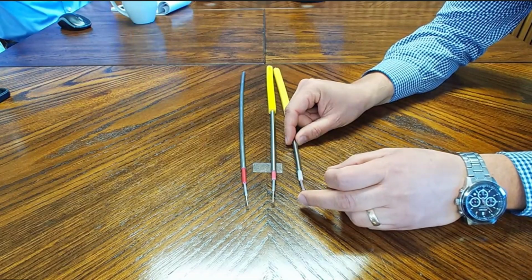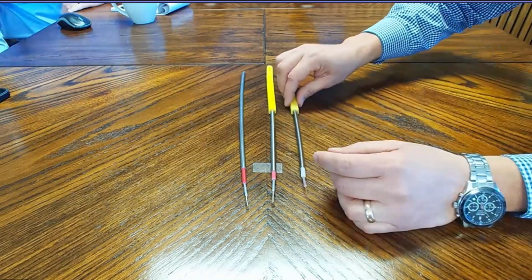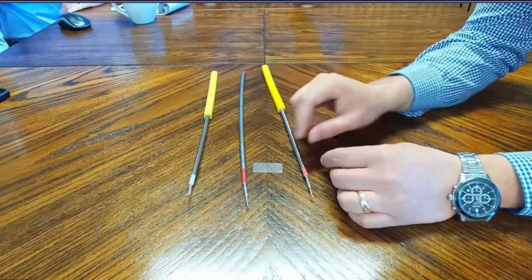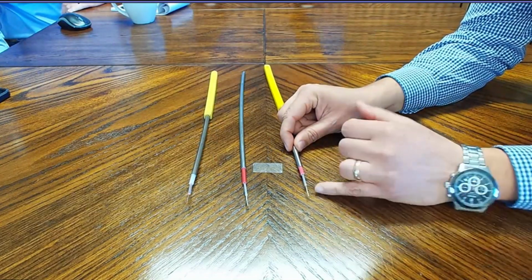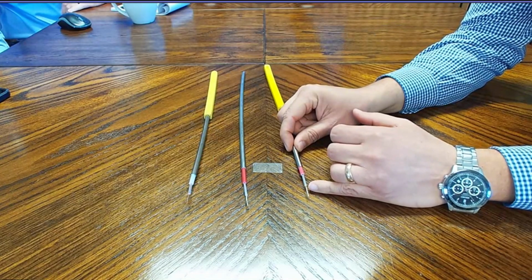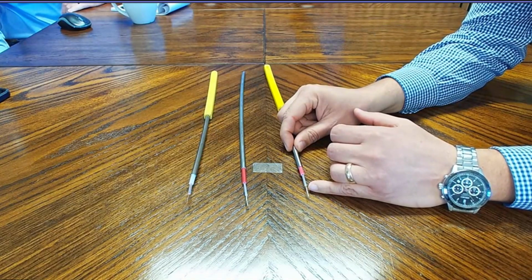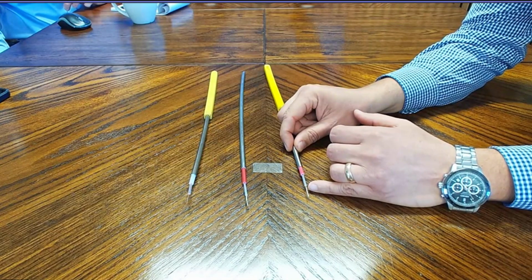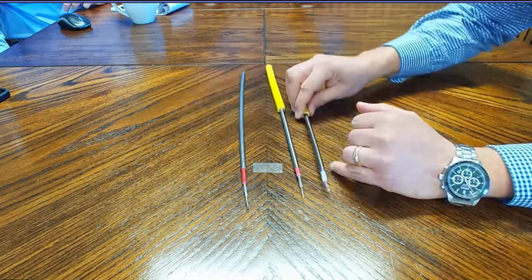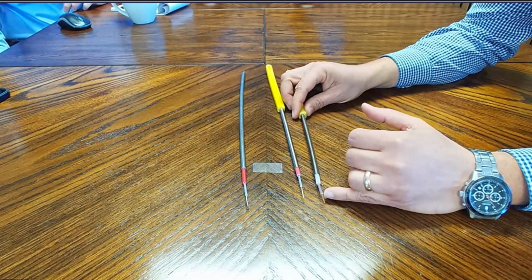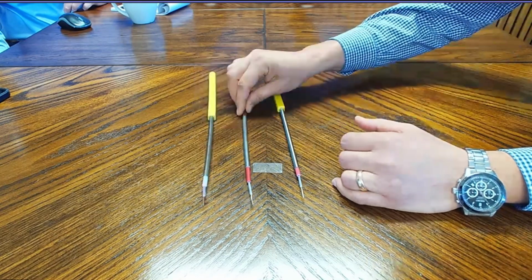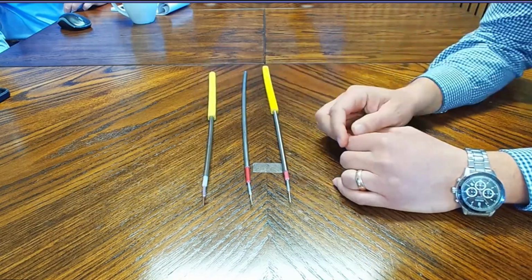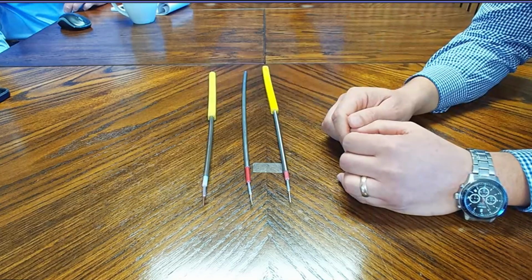However, here at Flowco, we prefer to use the 18 gauge conductor, because it's more flexible, so it's more forgiving with vibration. Also, if one of these little wires breaks, you have 6 more holding that electrical connection to the gauge. Whereas the 16 gauge is just one wire. If this breaks, then you have no electrical connection with the gauge. That's the reason why we prefer here at Flowco using the 18 gauge 7-strand tin coated conductor.